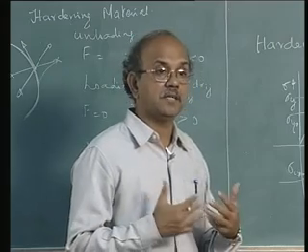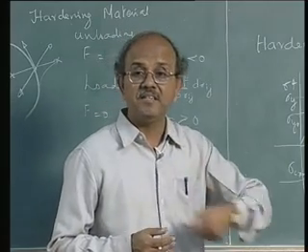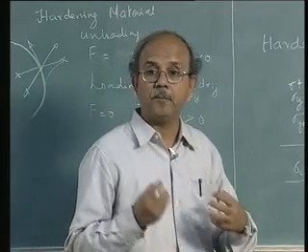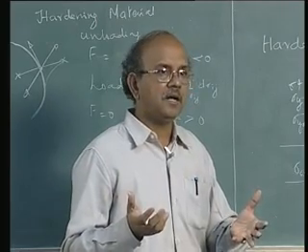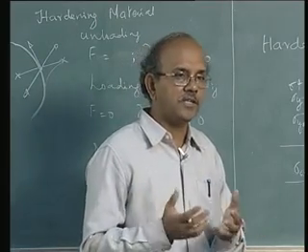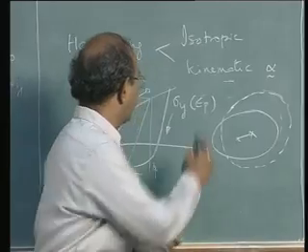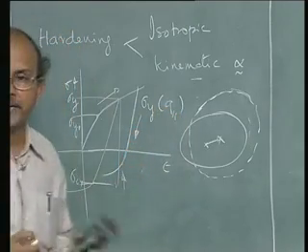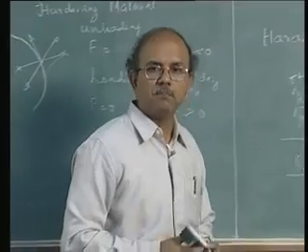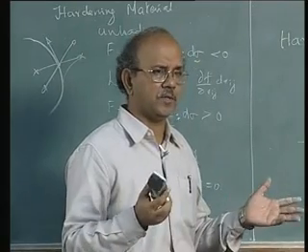It can be viewed as an internal variable, or in other words, whatever is happening internally is now depicted in terms of εp, may or may not be the case, and it is a common practice to write down internal variables as something like qi, and say σy is a function of qi. But in many practical situations, again, σy is expressed only in terms of εp, by various equations.